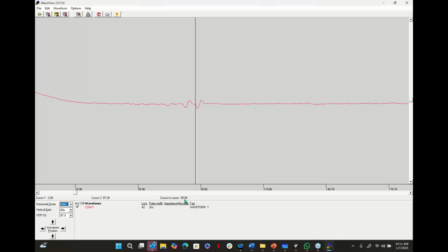Two separate S-curves. Now, let me jump straight to the end and tell you what this was. This was actually two dings in the hardline cable. It was that easy to find, but I was in a 2 nanosecond pulse width, all right? Can you understand how if I were in 100 nanosecond pulse width, I might not see something that small? But can you see how if this were in maybe a 25 nanosecond pulse width, I still might see it, but at a few feet apart, it may only appear as one? You see what I'm saying? So that's what this problem was right here.